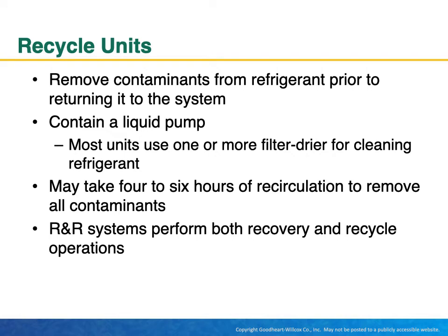Recycle units. Remove contaminants from refrigerant prior to returning into system. Contain a liquid pump. Most units use one or more filter dryers for cleaning refrigerant. May take 4 to 6 hours of recirculation to remove all contaminants. R&R systems perform both recovery and recycle operations.